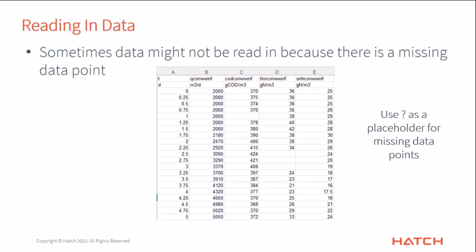In this case, you need to do something about these things. If you leave them blank, then the spreadsheet will not be read in correctly. What you need to do is actually insert a question mark. It is a placeholder so that GPSX knows exactly how all of the data points fit together. And you can use that placeholder in the spot of anything that you don't know, so a blank spot that would be in your data sheet.